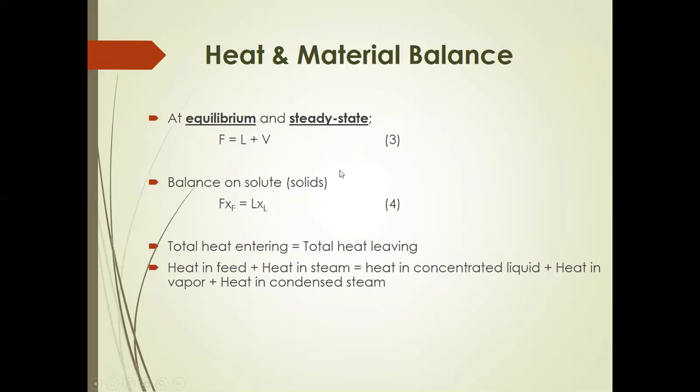If the problem does not mention any entrainment, there isn't any value for the YV, because YV will only have a value when there is entrainment, and that is if some solids are carried over by the vapor as it goes up your evaporator. Most of the time, 98-99%, there's no entrainment. Then when you balance the solids, it will only have two terms on the left side and the right side of the equation.